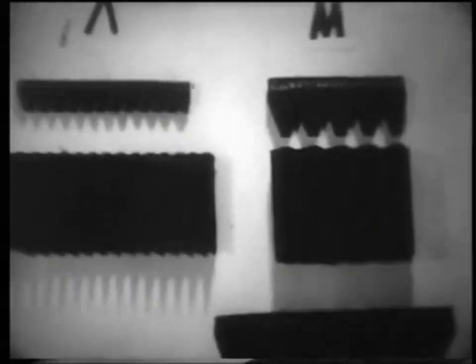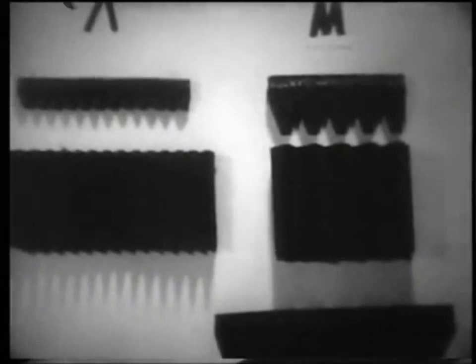The transmission with several V-belts on the pulley is affected by the heterogeneity of the elastic properties and sizes of different belts that are not equally located in the grooves. The gear ratios of individual belts can be different and the load on the belts is distributed unevenly. On V-ribbed belts consisting of a flat part and wedge projections, an error in the size of individual ribs does not affect the location of the cord along the entire width of the belt. This ensures a quieter transmission operation and a greater load capacity.